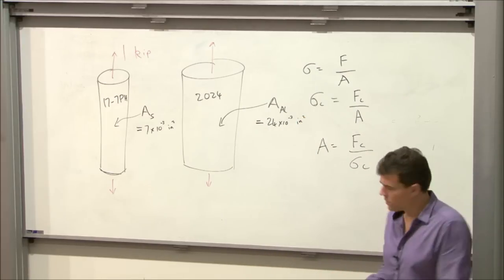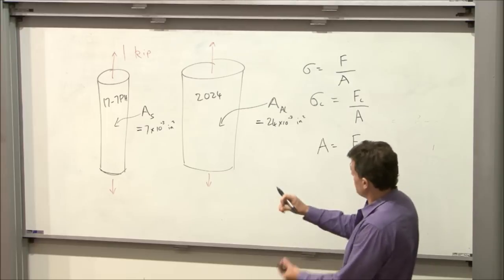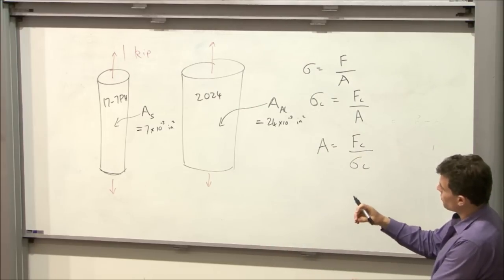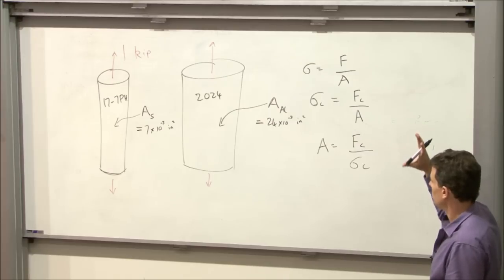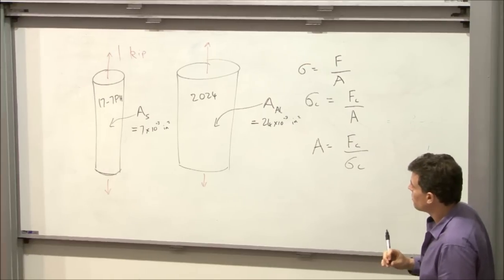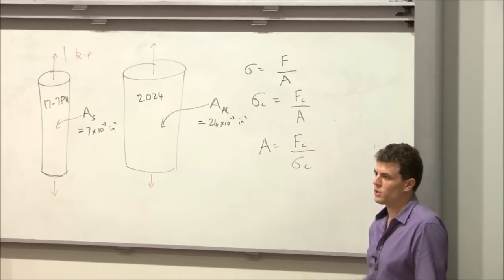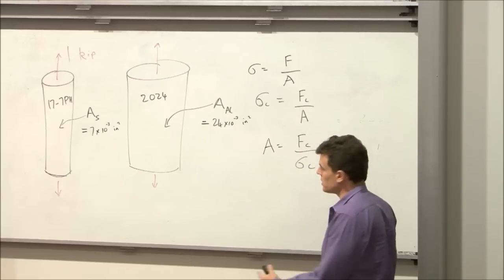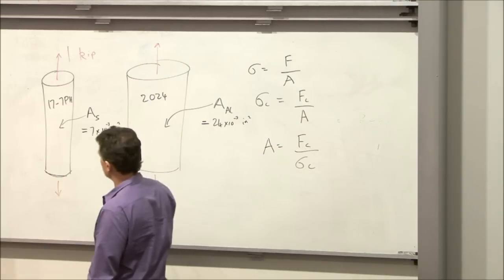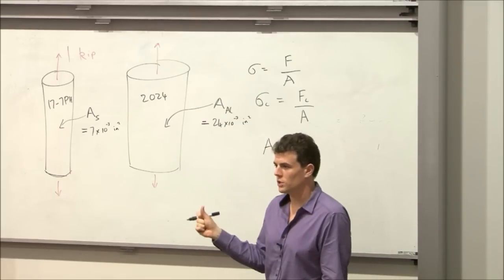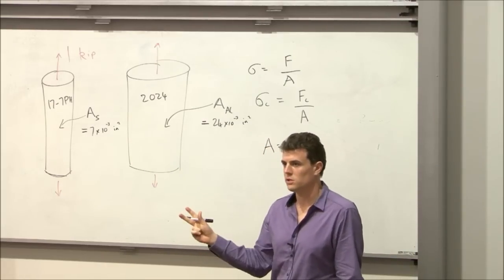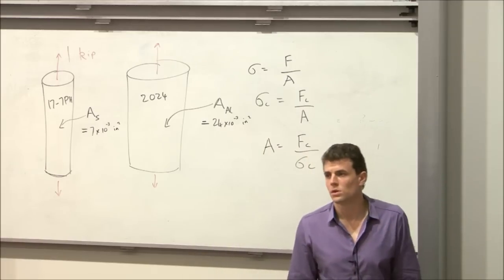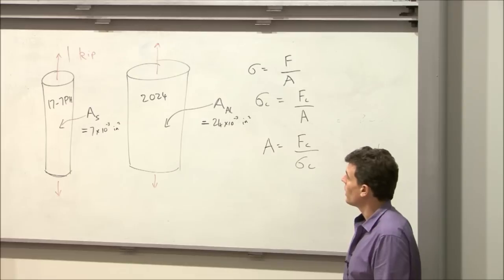Okay. Now, let's assume that each one of these, so these are wires basically, they're not rods, but let's just assume that we've got, say, what's about a meter? Say 40 inches of each one. Now, which one's going to weigh the least? So if we want to work out the weight of each one, we take the cross-sectional area times the length times the density. So you've got the density up there in pounds per cubic inch, so we can work out the weight of each rod.